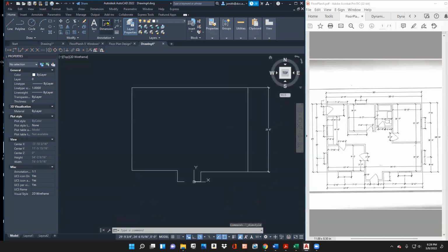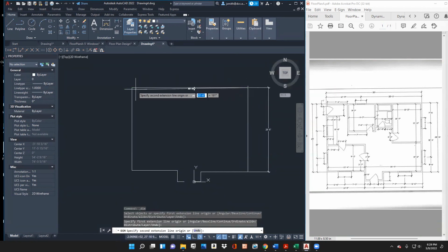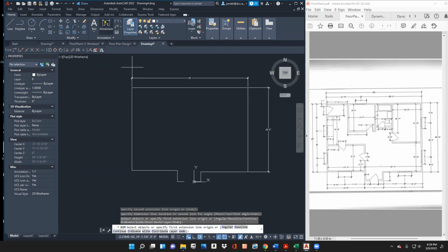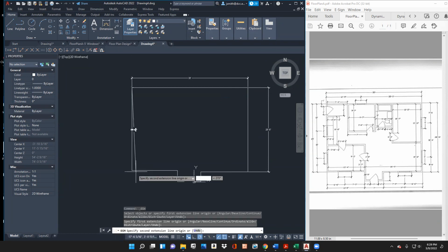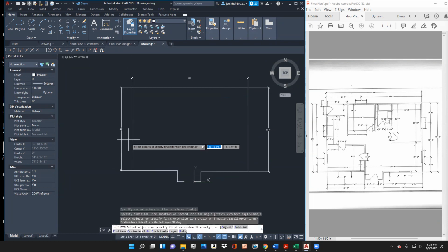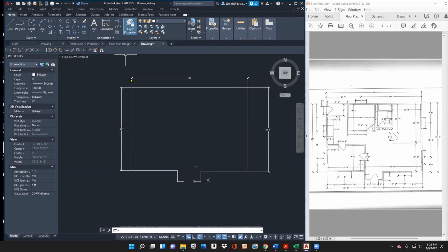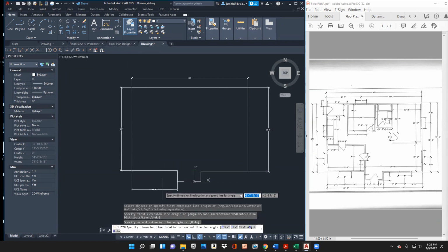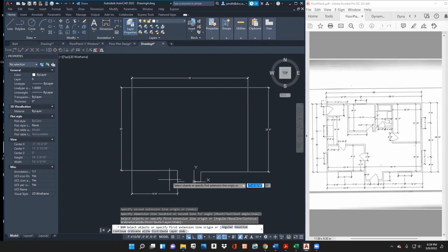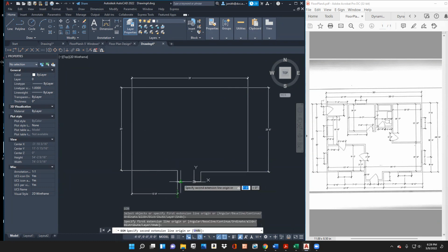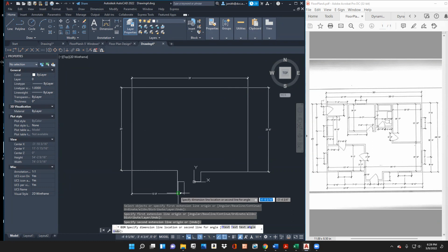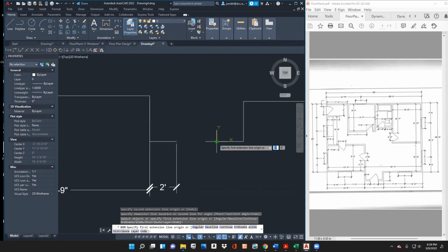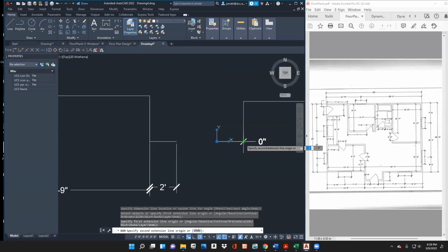And so let's just very quickly, I shouldn't say quickly, but I'm going to go rather quickly, just verify my dimensions so I'm not wasting time later fixing things. 25 feet, enter. So if I just select enter, it'll do the last command. Enter twice. This is 2 feet. And I should then come here. This should also be 2 feet.